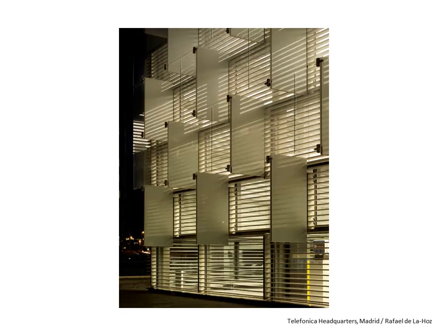Some of you have already done these for your precedent study. We did some things with Louvers, right? Now, Louvers is a very simple idea. It's just a shading device. You can have static Louvers, which are essentially designed to accommodate a range of times, so that most of the time they are shading you from the sun. They may not work all the time. They may be shading you all the time, but then they get very deep, and that may affect the aesthetics of the space. This is a project that I think some of you had, like Telephonic headquarters.